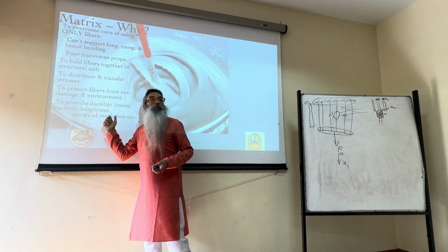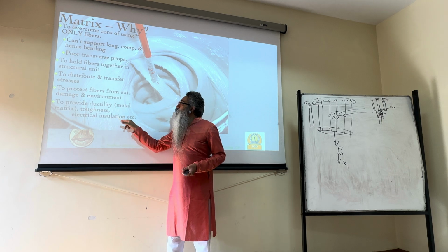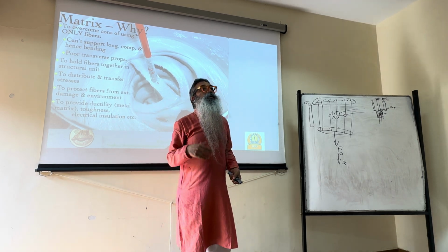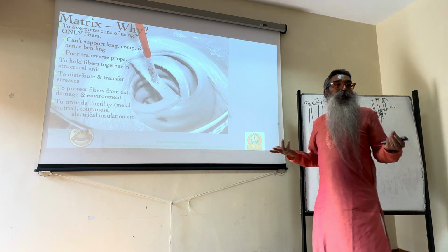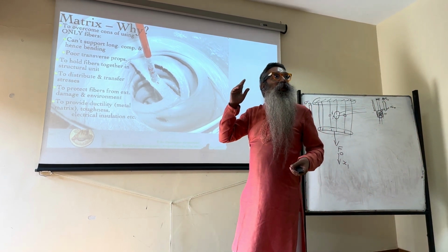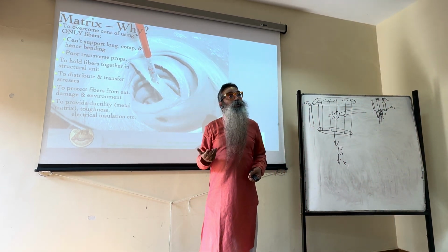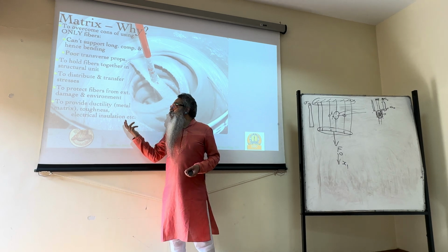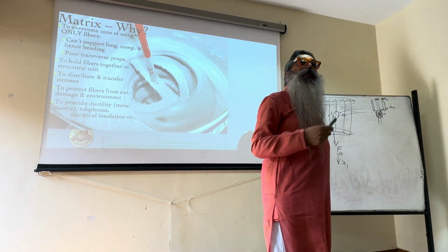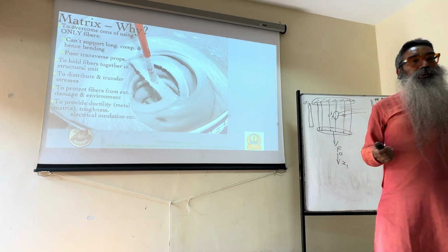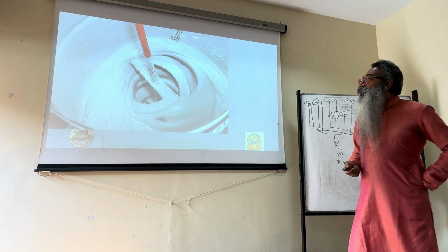But with metal matrix, that can be increased, right? Similarly, in terms of electrical insulation, especially if you want conduction, then metal matrix is good. If you want, let's say, insulation, polymer matrix is good. Even ceramic matrices, which are very good insulators, are good enough. So you can essentially bring in these aspects also depending upon the specific matrix that you choose.